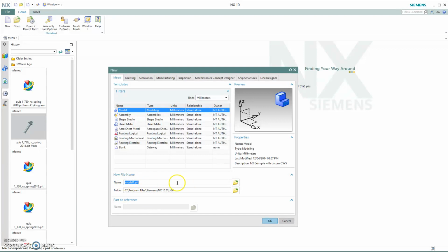Name. This is important, so you always want to rename it here, okay? So don't save it to your desktop and then rename afterwards, because NX will get confused whenever you're doing assemblies, and then it's a whole thing. So really, we also give you the file names, so just go ahead and start that way. I'm just going to put lecture 1 Welsh Zachary, and that's how you should be doing it all the time.